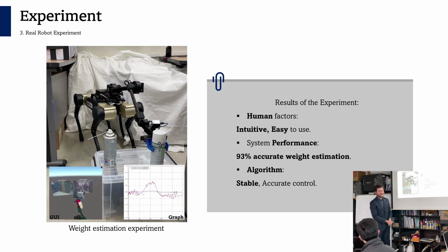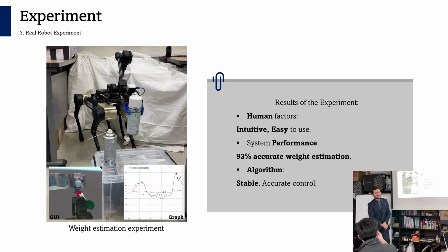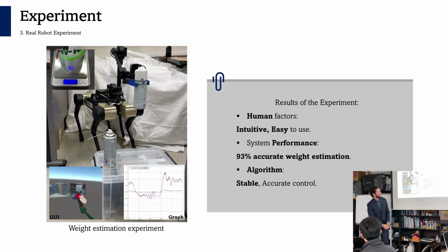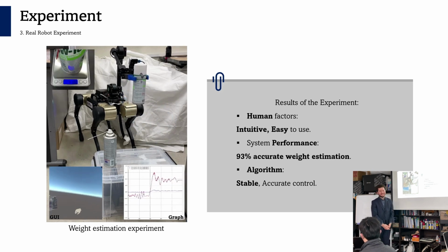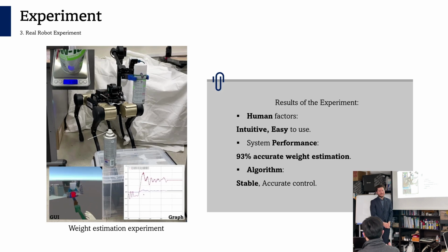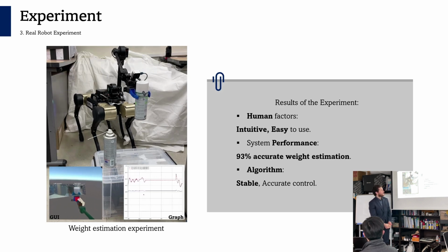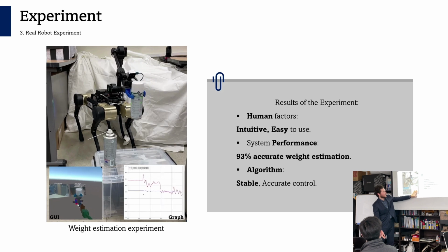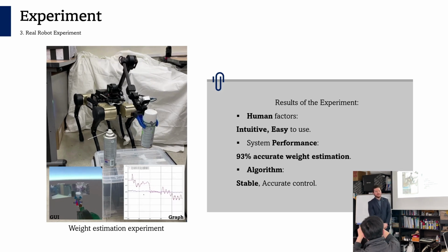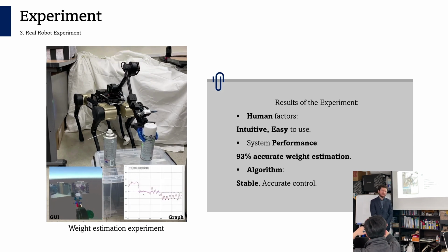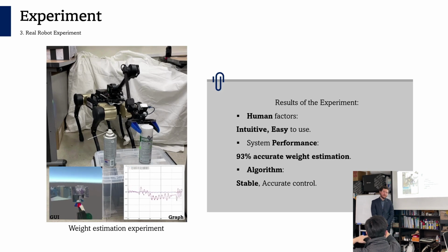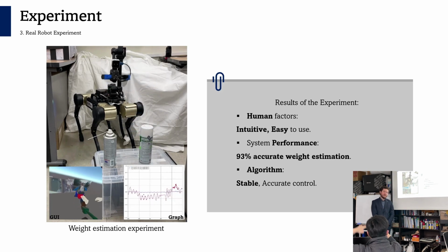And maybe the main reason for this oscillatory motion is that your compliance controller does not have a damper in the end effector. Yes, it doesn't have end effector damping. So that might be one reason for the vertical oscillation. Mostly your desired position is located here, but the gravity is making your end effector move a little bit lower, and there might be a vertical oscillation.